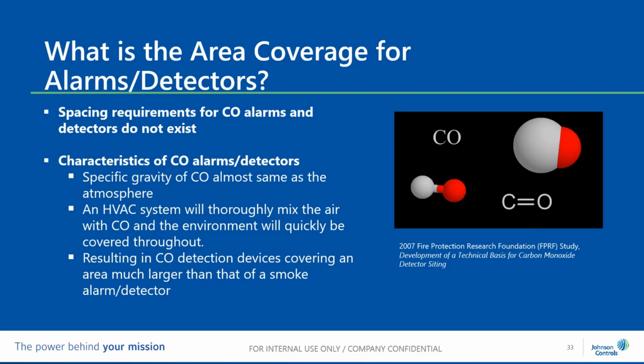And some are getting that because they might be saying, well, I have smoke detectors and the smoke detector has a carbon monoxide device with it, and a smoke detector is every 30 feet, so therefore carbon monoxides are every 30 feet, or carbon monoxide in the heat detector, and it's every 50 feet. That's not the case. It's only required in certain areas in the HVAC zone, above the fuel burning appliance, one on every floor, but there are no spacing requirements for CO.